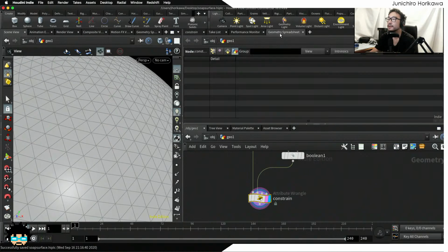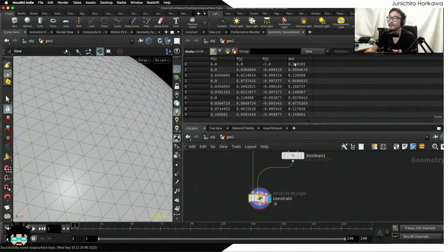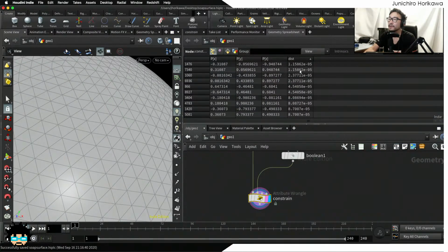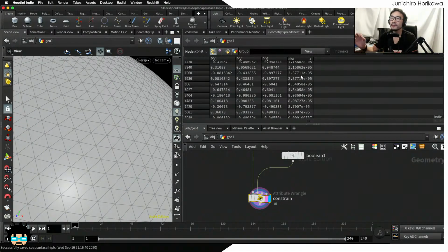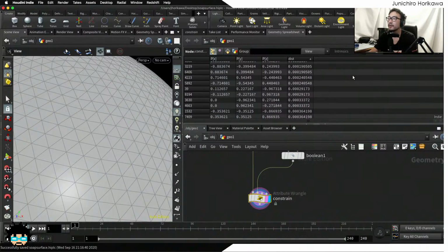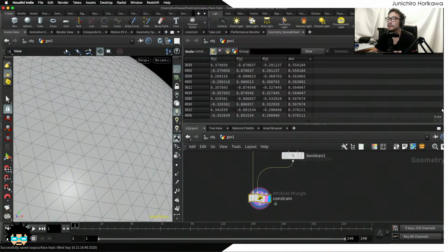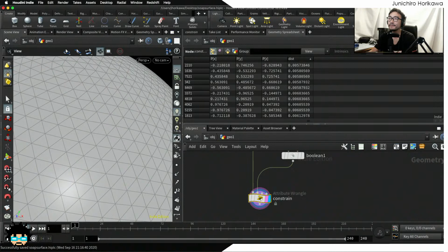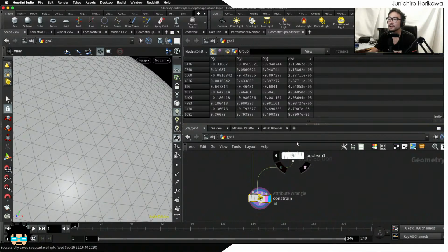Okay, so go to the geometry spreadsheet, to the point tab. You'll have a new dist attribute, and the minimum seems to be really close to 0 and the maximum is around 0.5. Obviously the distance that is close to 0 should be fixed because the point is on top of the edge. But the distance that is far from 0, like 0.5, shouldn't be fixed, should be really flexible. By checking it, maybe 0.01 or 0.05 is a good number to fix. Not sure. Maybe you want to also precisely change that with some parameters.